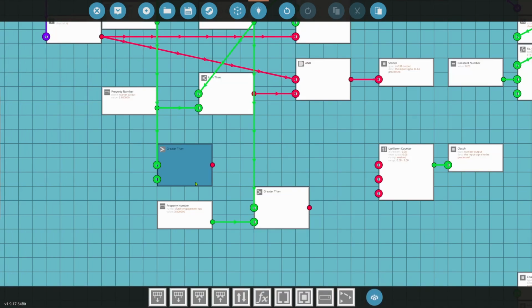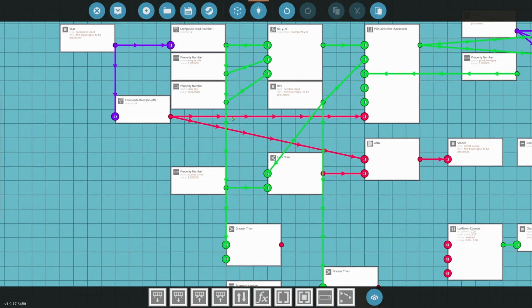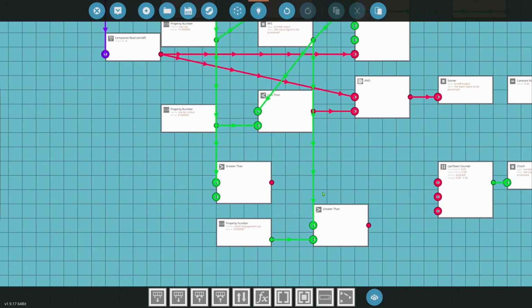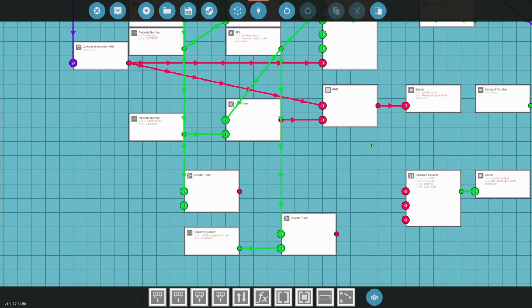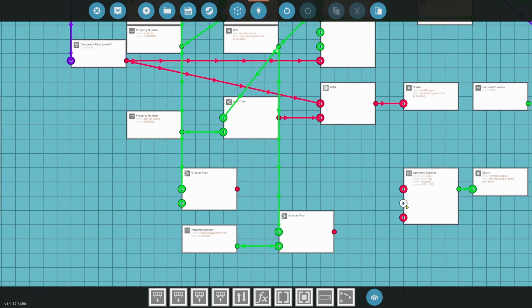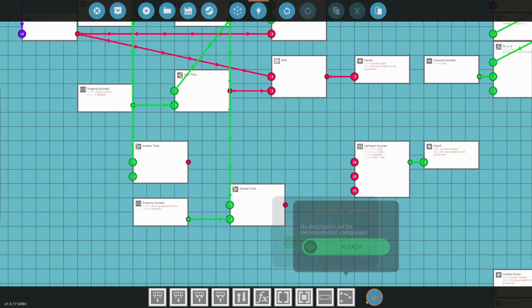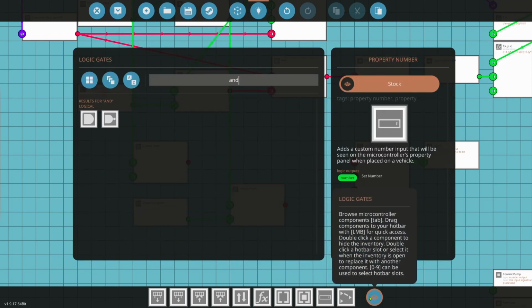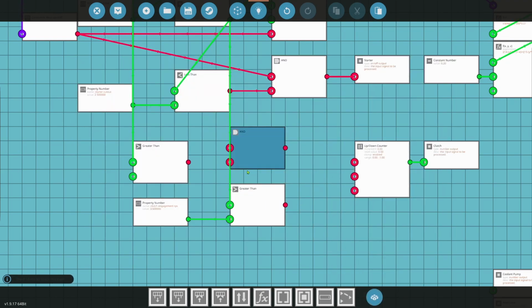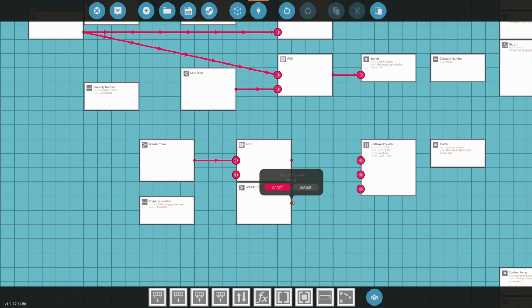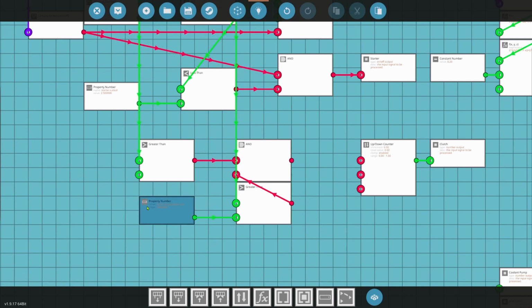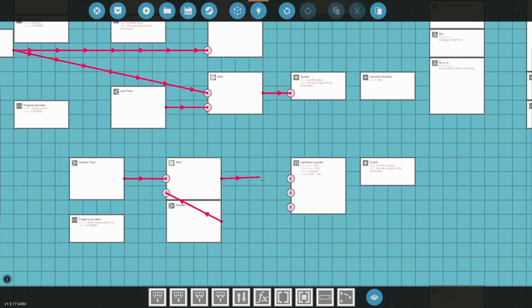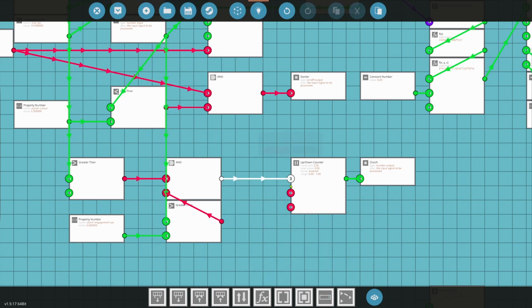In this case, if we're asking to go forward, so if our W key is pressed down, and the RPS is greater than 3.5, we're making enough power to go forward. That's when we want to start increasing our clutch and putting our clutch in. So we're going to take an AND and plumb the AND in here. If the W key is greater than 0, and if the RPS is greater than 3.5, we want to increase the up-down counter.